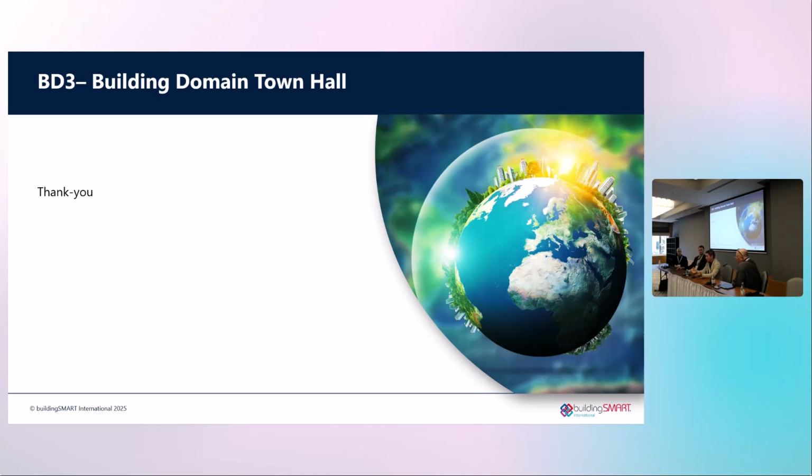Some experts use IFC space, which is a little tricky because you need an enclosed area with doors. But with IFC spatial zone, you can put simple geometry, map it with IFC spatial zone, and say secure, don't step in. That's a dangerous area, an area of manufacturing.